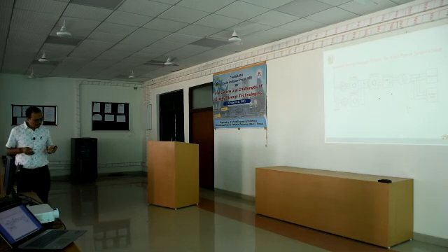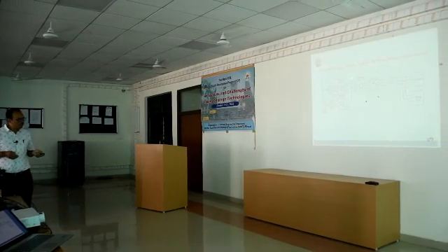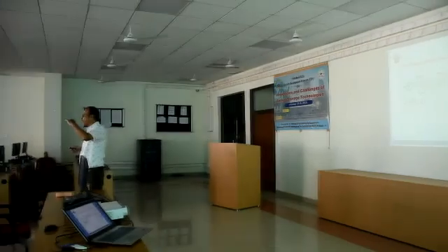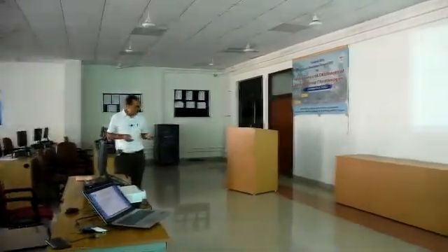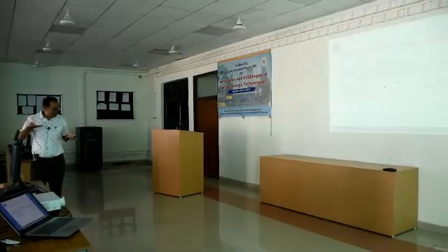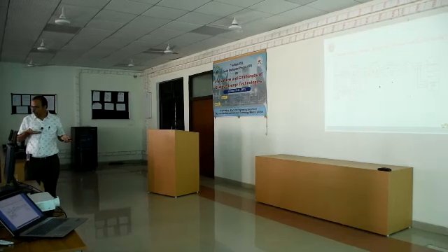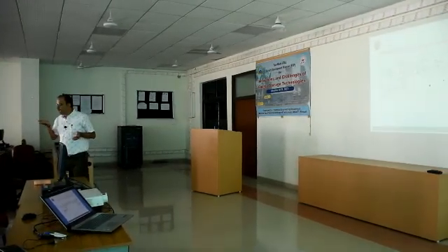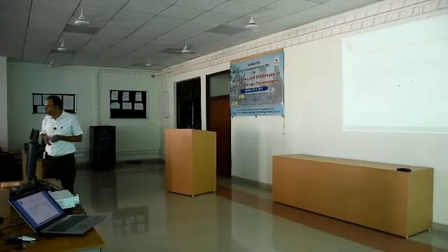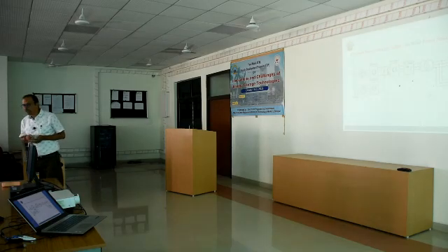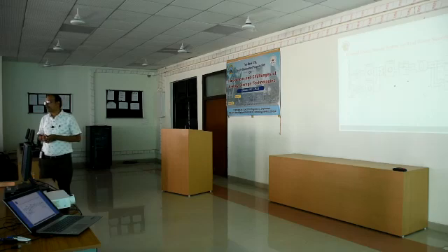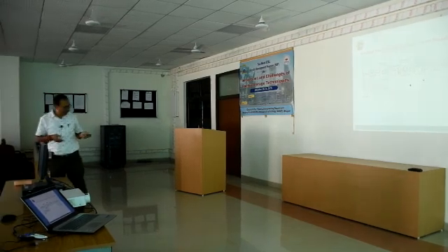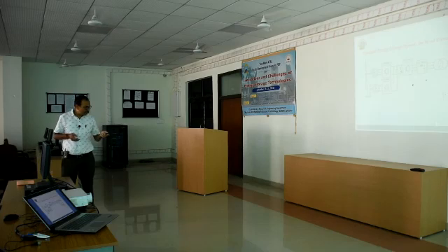So what was suggested in this work is that you absorb the value above your average value through a flywheel system. When momentary excess power is coming, this excess power goes to your flywheel through this induction motor drive. Energy is stored, the speed increases, and the flywheel stores the energy in the form of kinetic energy. And when there is a fall in the power because of 3p oscillations of the wind turbine, you supply the energy back. So at this capacitor, at the intersection point, you will have a steady power supply. When there is deficient power from this end, you feed power through this, and when there is excess power, you absorb it.